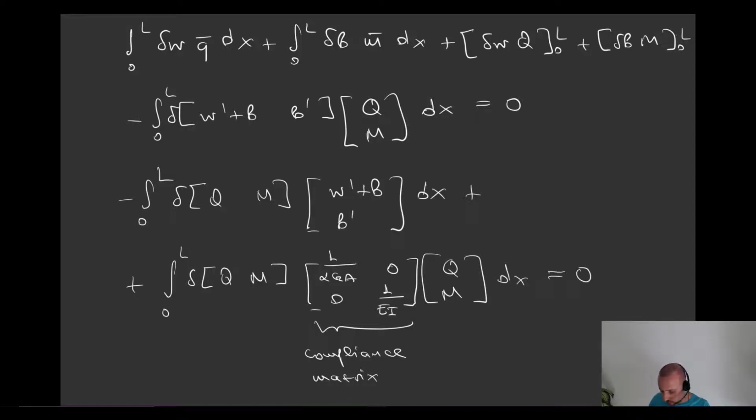Okay, this slide contains all the essence of the Hellinger-Reissner variational formulation for the Timoshenko beam problem. Please take a note on this, and just recall that we have two equation systems in this case, where we seek for 4 unknowns in contrast to what we had in the first chapter. We seek for both the primal unknowns, which are the vertical deflections and the cross-sectional rotations, along with the reaction transverse shear forces and the reaction bending moments. So in total, we have 4 fields that we seek for, and therefore we have to have a corresponding number of equations to be able to solve for.